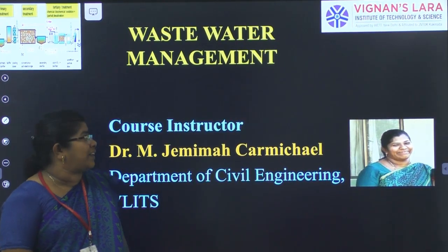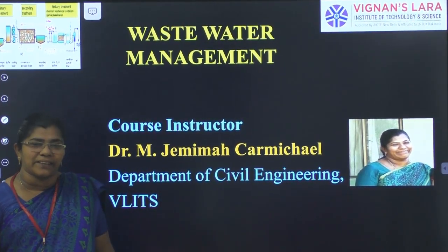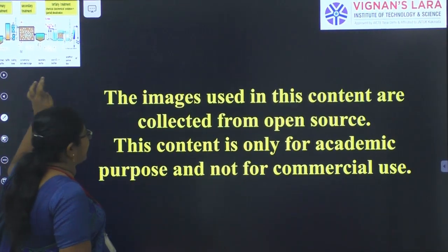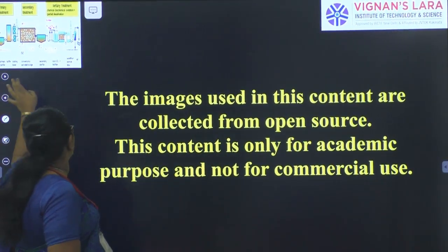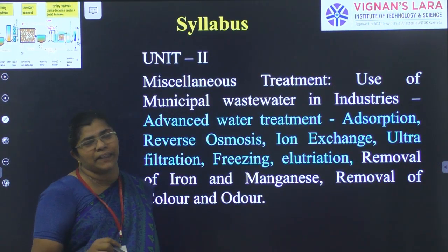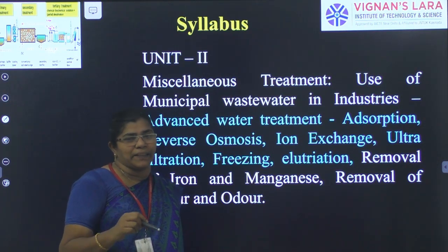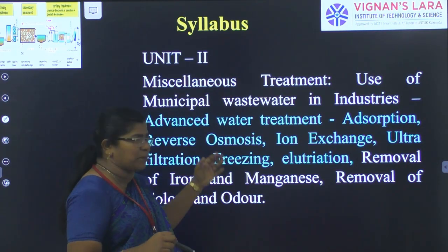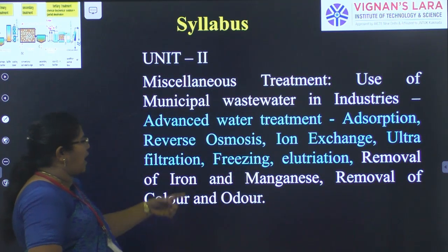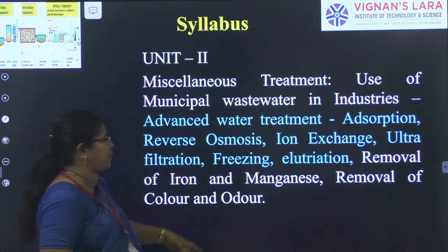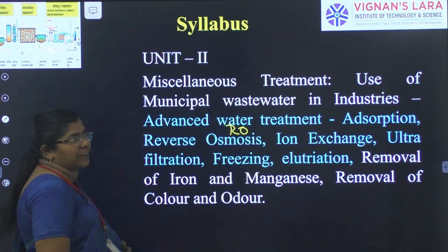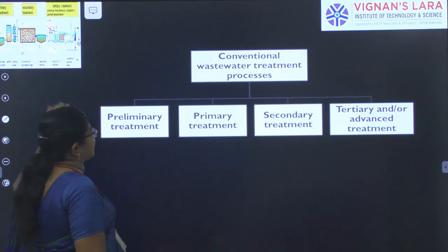Welcome students. In wastewater management, we are now in the second unit, the treatment methods. Last class we saw preliminary treatment and primary treatment. Now we are going to see the tertiary treatment, or as we call it, advanced water treatment: adsorption, reverse osmosis, or RO, ion exchange, ultrafiltration, freezing and filtration.